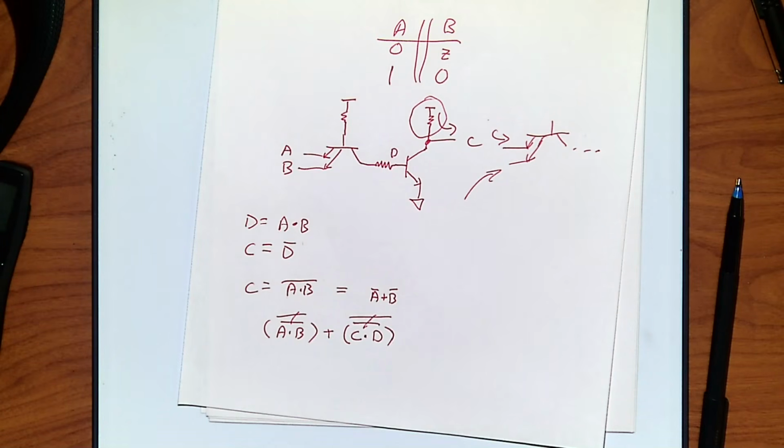So this open collector idea was the first way buses were built, and that basic idea is still needed on a bus today. However you do it, you can do a similar thing with FETs, and we'll talk about that later too. But it makes sense here as a first intro. So that's the other reason it came in. Number one, you could do wired logic, so you can make bigger gates by hooking them together.